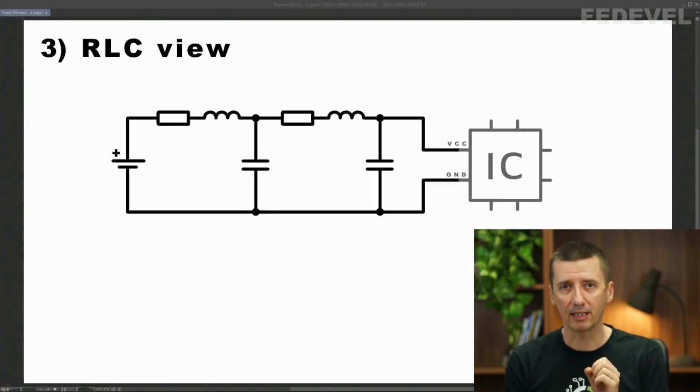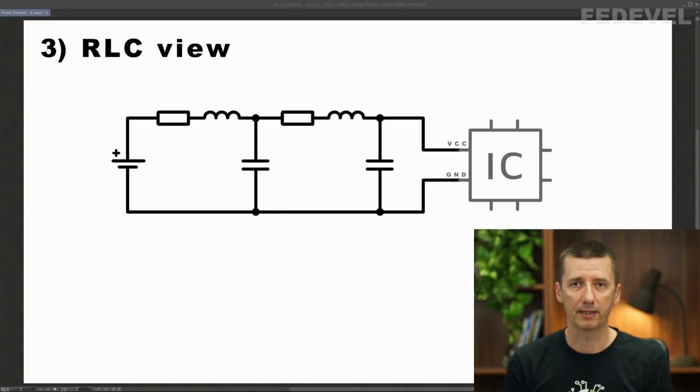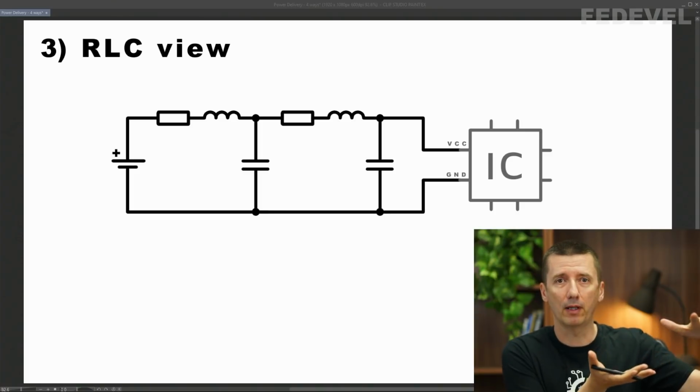However, for power delivery, every small inductance will influence how power is delivered to your chip. Only the question is if it's going to be a problem for your chip or not. And it's not only about inductors, it's same for capacitors. On real PCB, there will be, for example, many decoupling capacitors, which you may want to consider. They will be all connected to your power. But also don't forget about capacitance between power planes.